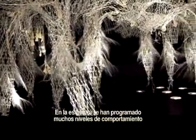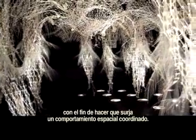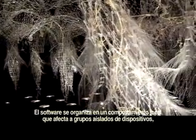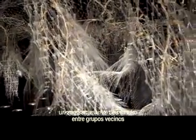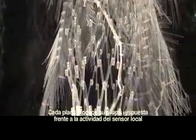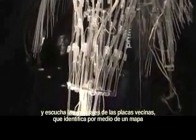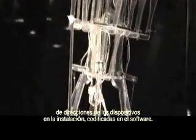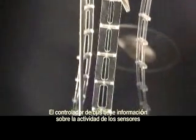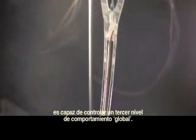Several levels of behavior are programmed into the sculpture in order to encourage coordinated spatial behavior to emerge. Software is organized into local behavior, affecting isolated groups of devices, coordinated behavior between neighboring groups, and global behavior, running throughout the whole system. Each board produces its own response to local sensor activity and listens for messages from neighboring boards, identified by means of an address map of the devices within the installation, encoded into the software. The bus controller has information about sensor activity from all of the individual boards and is able to control a third level of global behavior with this information.